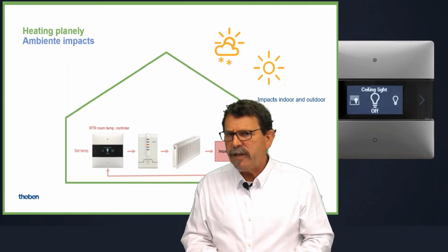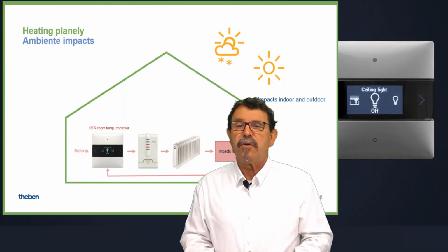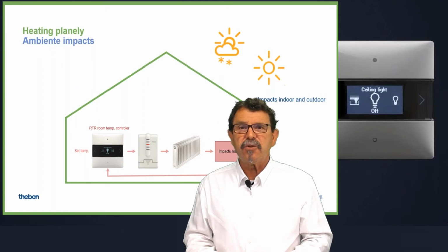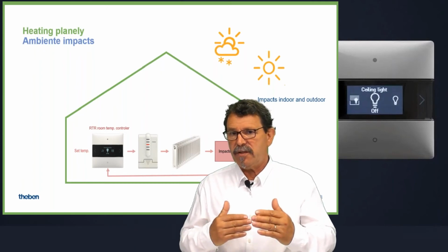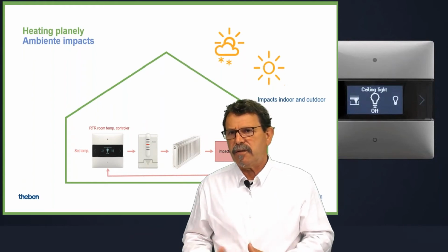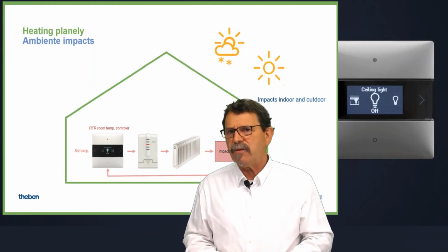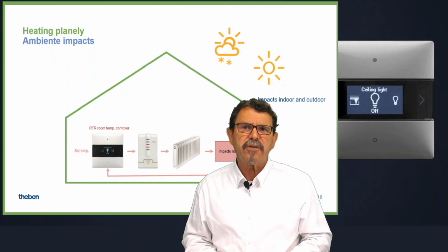When it comes to floor heating, floor cooling or ceiling cooling, the hysteresis control is good enough, because this procedure is rather slow, and due to that, hysteresis control is more than sufficient.